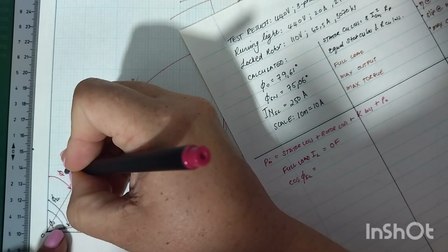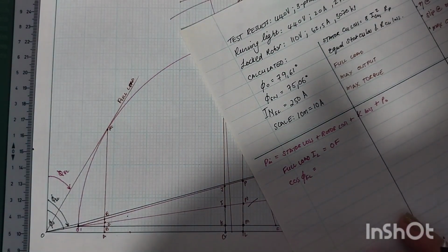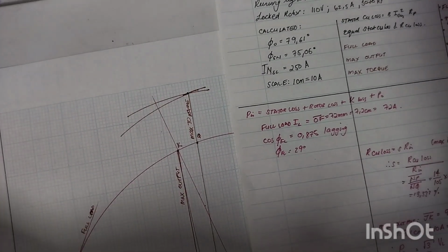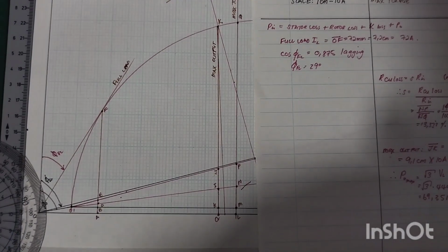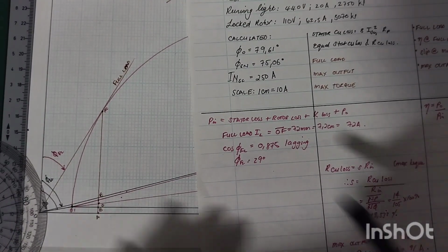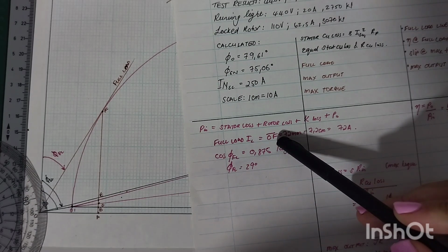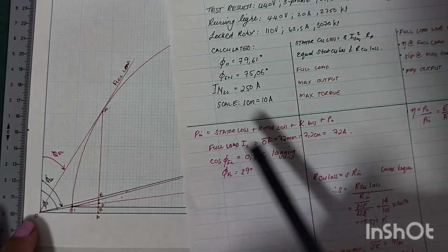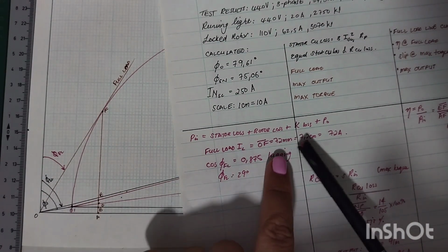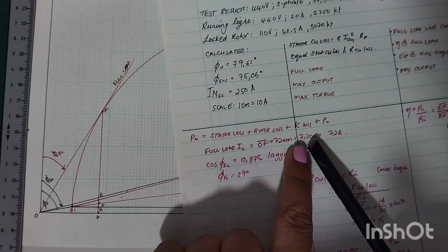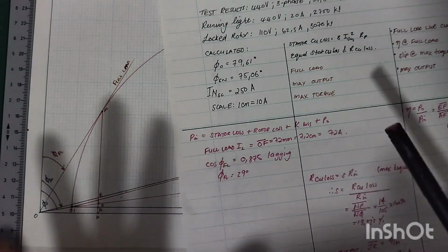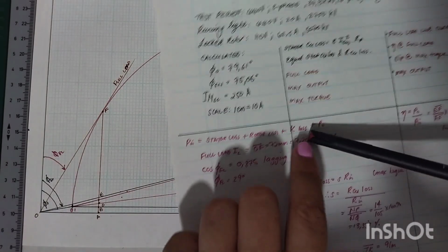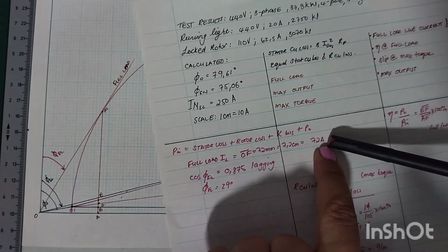And that would be your phase angle at full load. Okay, so once you've measured that line, I measured the tangent to my semicircle, which is my full load line. So from my origin to what I marked to be F now, that would be my input current at full load. I measured that to be about 72 millimeters, and because I use such an easy scale that 1 centimeter is equal to 10 amps, that is actually 72 amps. It won't always work out this way, but in this case it did absolutely wonderfully.